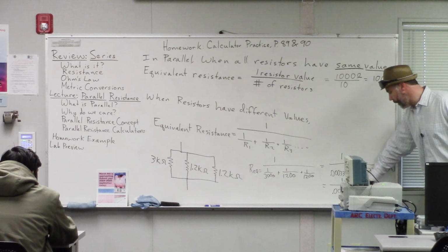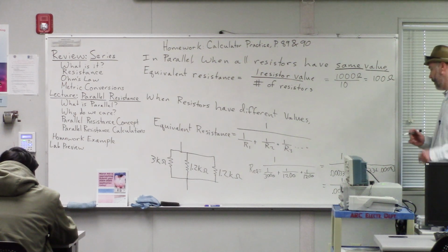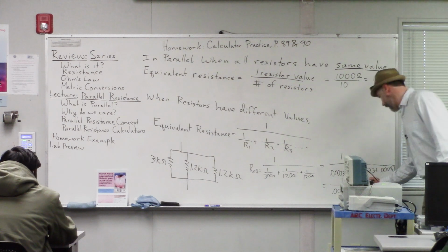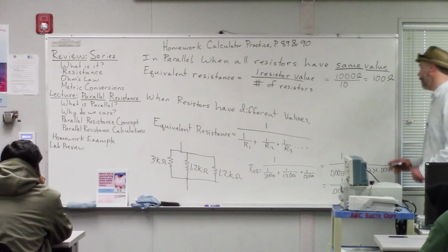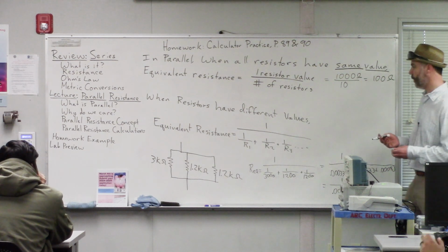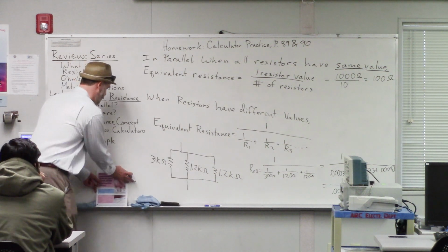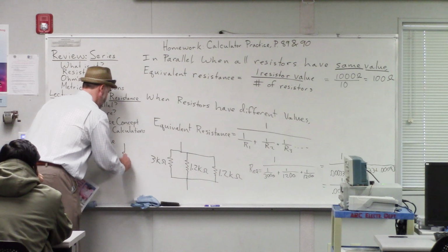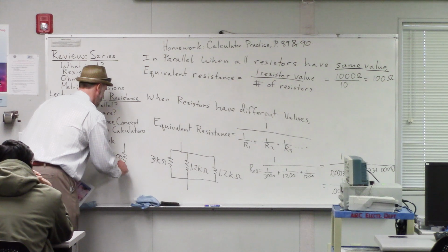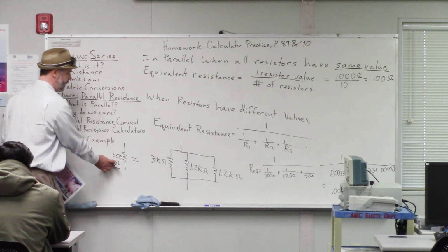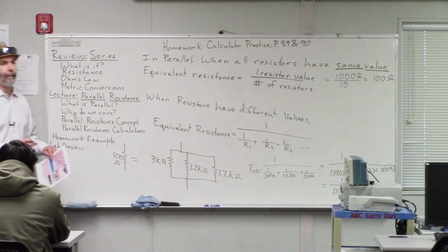And so then if I divide 1 by 0.002, what does that give me? 500. Okay, perfect. So that's the equivalent resistance for that circuit. It's 500 ohms. So if we had these three resistors in parallel, that's the same as just a single resistor that is 500 ohms. Again, this equivalent resistance is less than the smallest single resistor in our circuit. Okay?